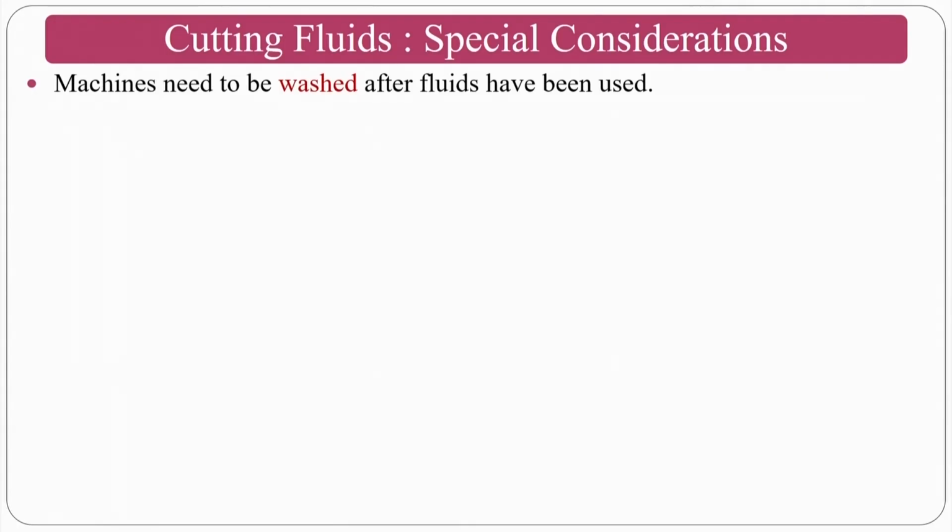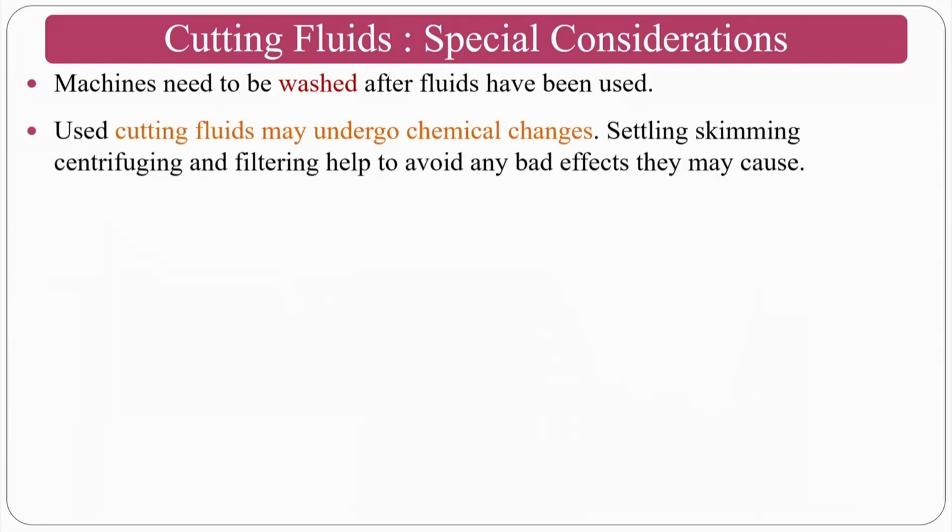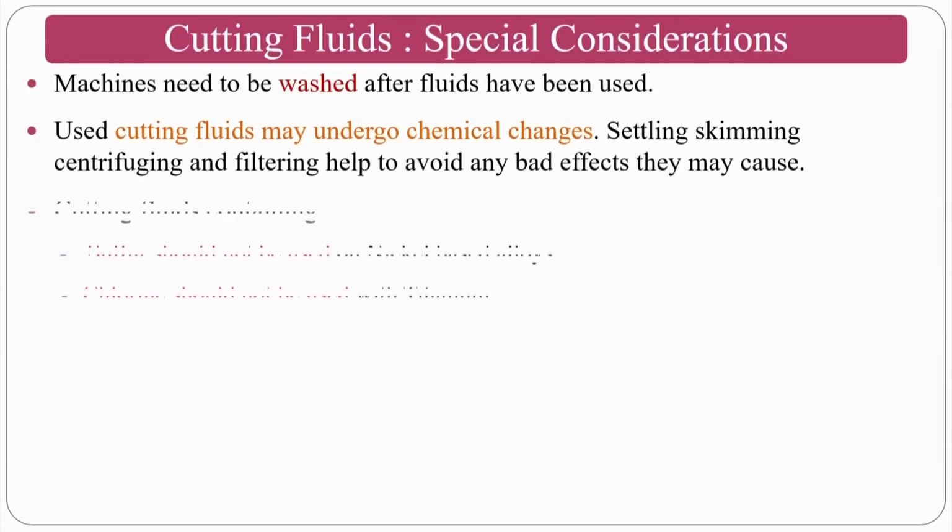Special considerations: machines need to be washed after the fluids have been used, because if you do not wash, it will be a problem. Cutting fluids may undergo chemical changes, because whenever you are using them the first time, the chemical composition may change. Whenever it comes to the high temperature region, chemical cracking will take place. If you are reusing again and again, the chemical cracking takes place again and again. So, the cutting fluid will undergo drastic changes.